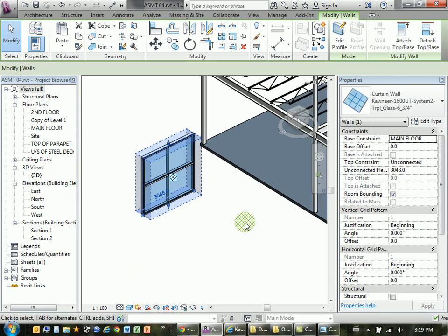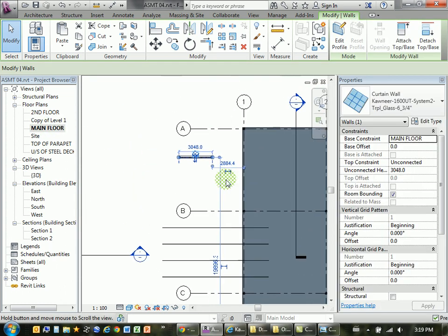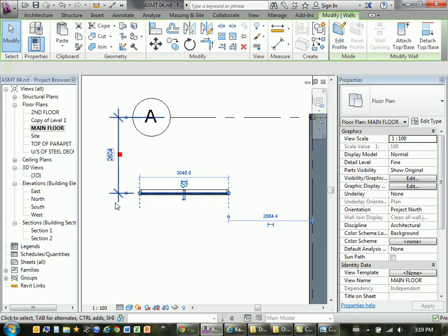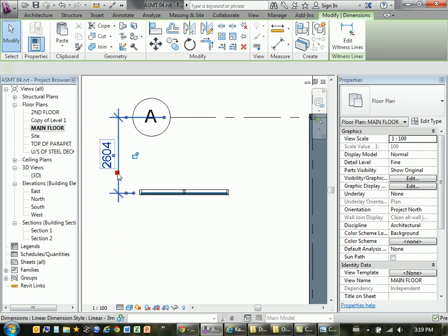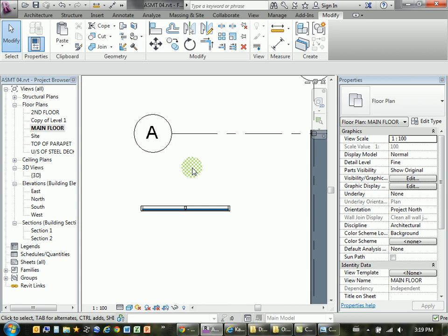First thing I got to do, of course, is just rotate it. So I want it to kind of align to this wall. So I'm going to go to my main floor view. And make sure, first thing I'm going to do is make sure that I've got my view range set properly. Sometimes when you do this, perhaps as a result of having worked on the beams, last time we had this project file open, we had a view range that was set really high so we could see those beams underneath the second floor. So just make sure that in your main floor with nothing selected,